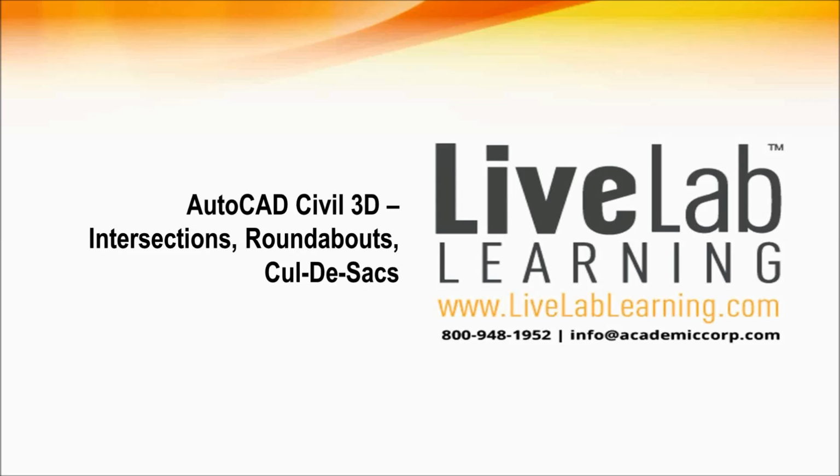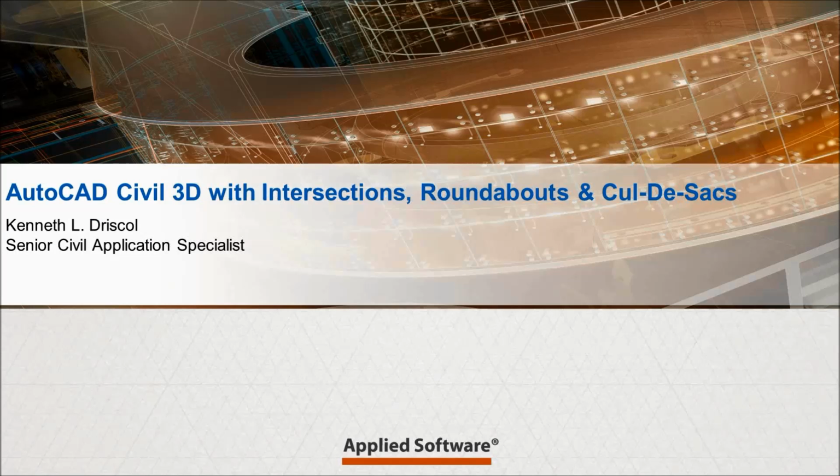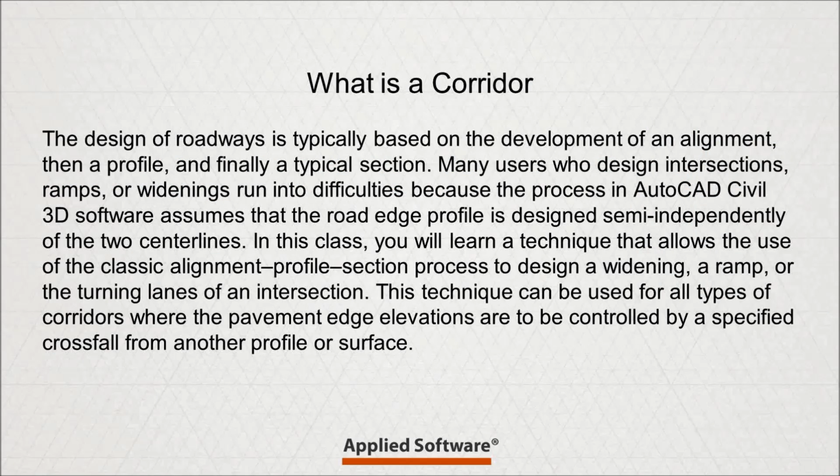Also, if we have time, I'll show you some of the more complex corridors that you'll be running into in reference to transportation and design within Civil 3D. So as I move on here, again, intersections, roundabouts, and cul-de-sacs. The first thing we want to consider is, if you haven't been using Civil 3D, you want to familiarize yourself with what a corridor is. And really, a corridor is the design of a roadway, specifically a typical section, based upon the development with an alignment, a profile, and then an assembly, which is a typical section.